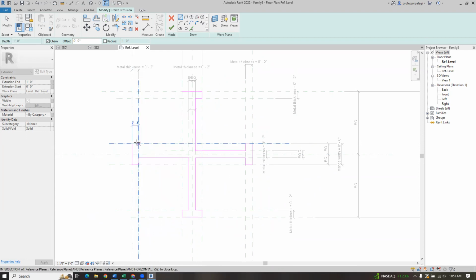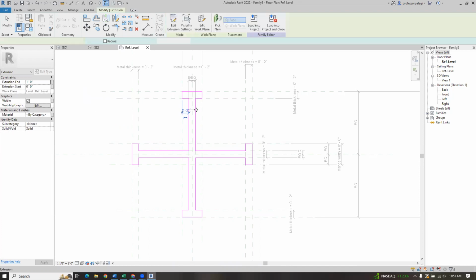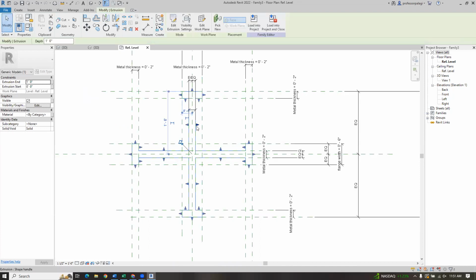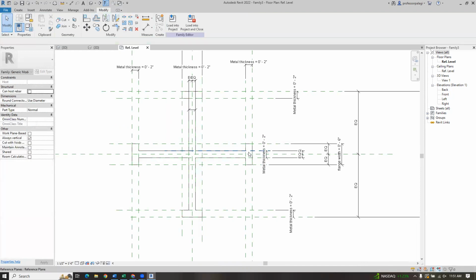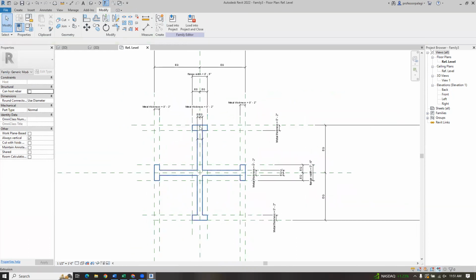We can go through and lock everything. You could lock everything to each one of these lines, but it knows it, because you see the green arrow snap on the corner. They have things called weak reference and strong reference. So this is weak reference, but nothing else, like I can pull it off, right? So you don't want that. We want reference under control because we're controlling reference lines. Right? So I just did that around and hit OK.